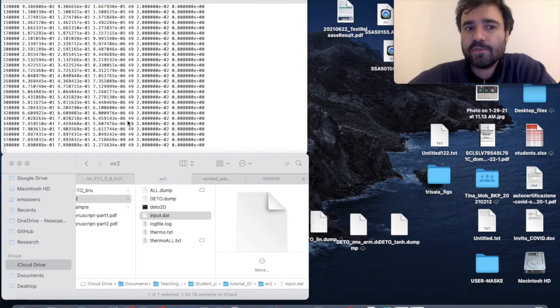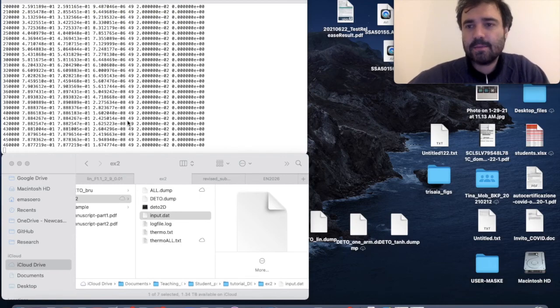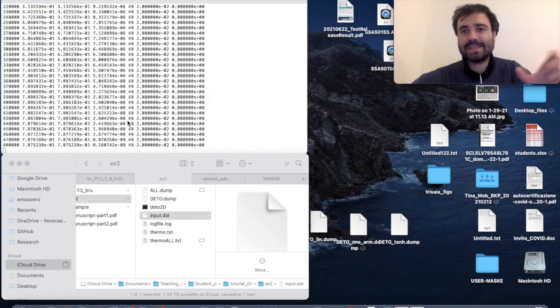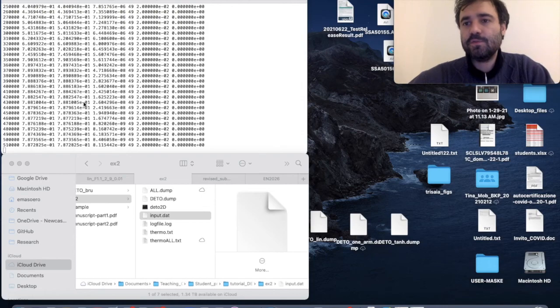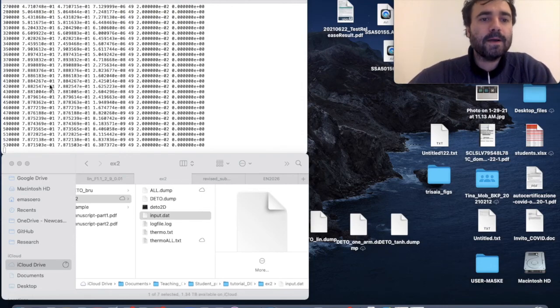It's something that you can often do in case, for instance, for any reason a simulation crashed, the computer turned off, and you want to restart the previous optimization, not from the beginning, but from the latest result that you obtained. Well, you can use exactly the same technique by imposing the same displacement, all the same conditions except of initializing the Xi from the previous dump file instead of initializing it from a uniform distribution.